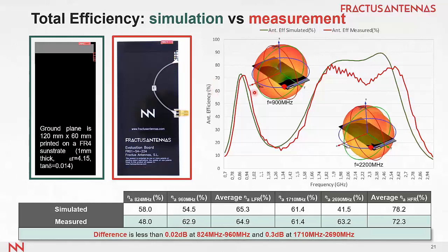Well, just a comment on radiation patterns. Naturally, CST can also handle radiation patterns, gain, and so on. Here, you can see that for these devices, the radiation patterns are usually omnidirectional with low directivities of about 2, 3, 4 dBi, which is good for wireless communication. It's ideal because you don't know where the base station is. So in the end, what you would like to have is some kind of isotropic radiation pattern in your IoT device.